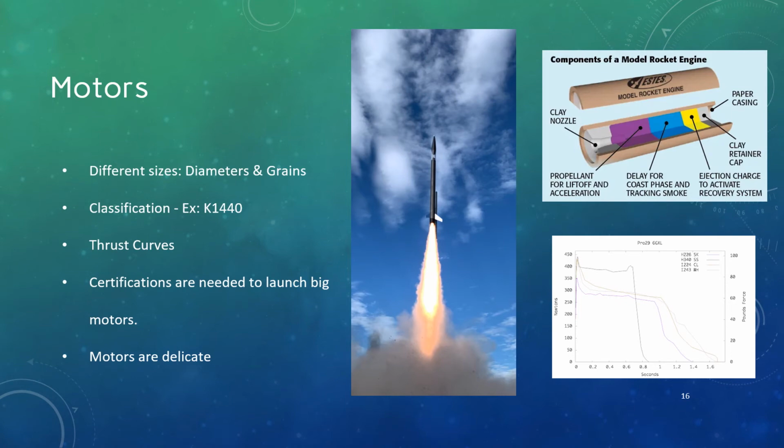So now for a review of solid propellant rocket motors. In Intro to Airframe, we'll only be using solid propellant motors. The other main type of rocket engines are liquid-based, which is the kind of liquid rocket engine group in AeroNU has experience with. But for solid propellant motors, different motor diameters and classes have different characteristics. The motors we use have different diameter values given in millimeters, so like 18 millimeters, 29, 54, and so on. Higher impulse motors have larger diameter motors, essentially.